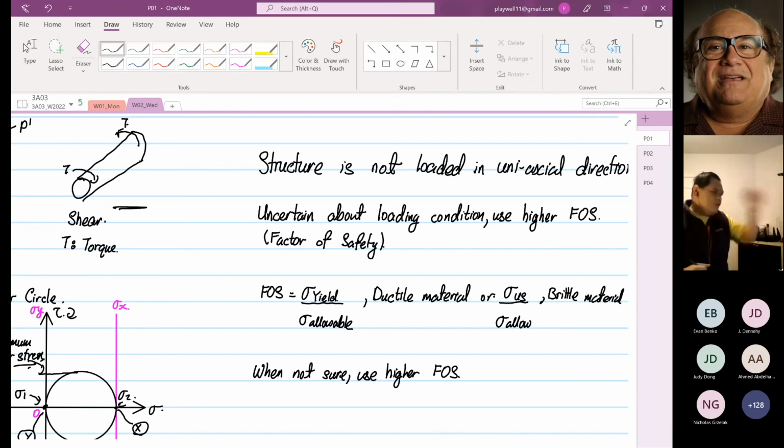That is where we cannot use a factor of safety that's too high. Civil engineers, oh, we can use a factor of safety of 3, 4. Your building isn't going anywhere, except you might get some earthquake, right? So for us as mechanical engineers, we design things that move, fly, go under the water, whatsoever. So we cannot use a very high factor of safety.